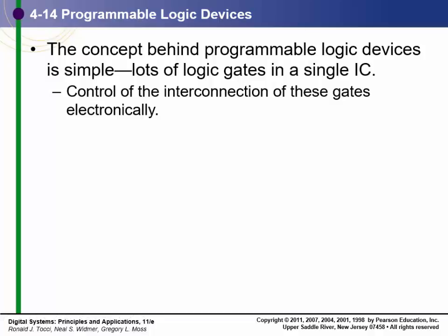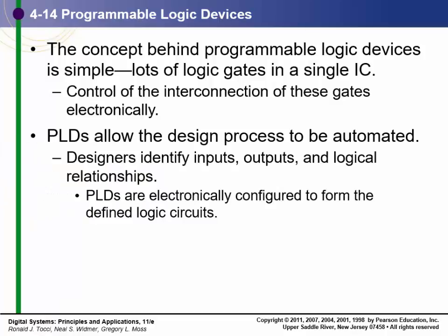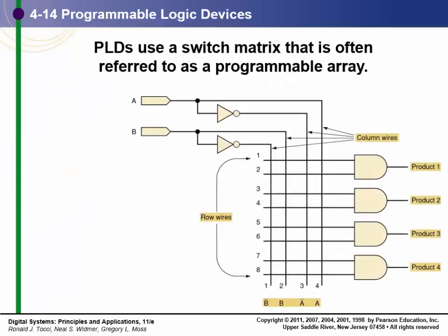Programmable logic, PLDs, is something we kind of introduced. This is a good drawing of a switch matrix for a programmable logic array. We have 2 inputs, A and B. We have 2 inverters. This rail is B naught.